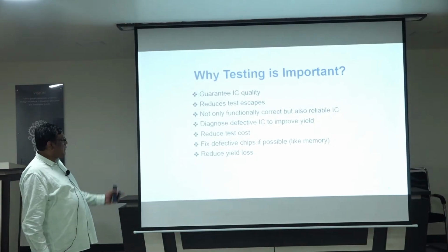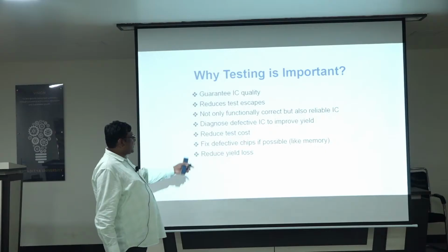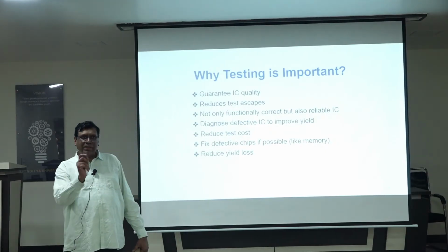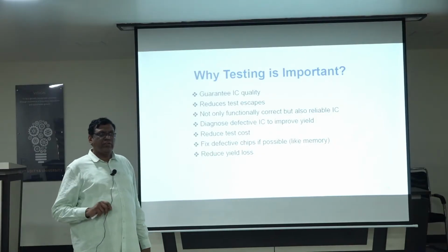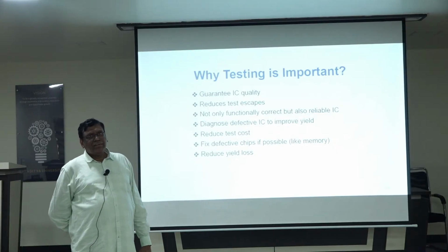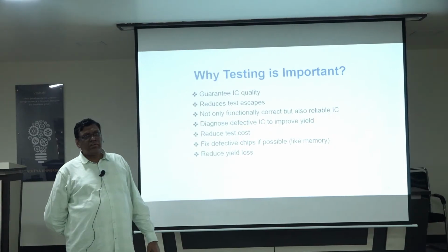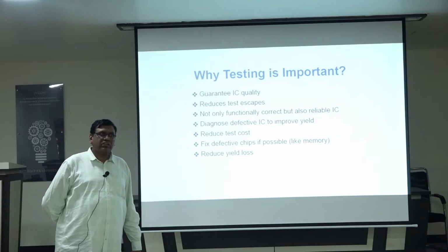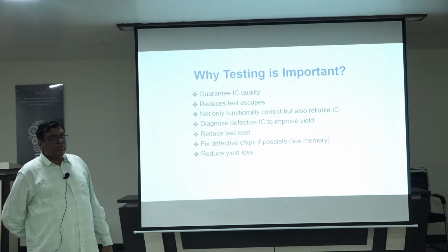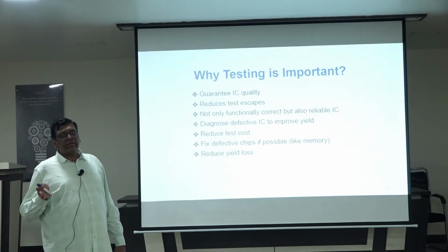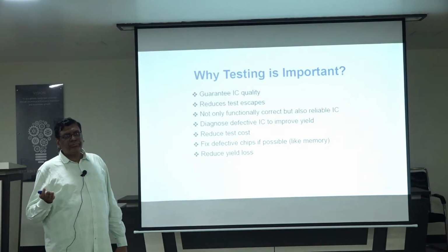Okay, so maybe it should fix defective chips if possible. Can you fix a chip? Suppose some damage has happened inside a chip. Can you fix it? We can't, but still we can do it. That is possible in the case of memories. We have a concept like repairable memories, where a few bits can be corrected. Extra rows and columns will be provided like a spare.